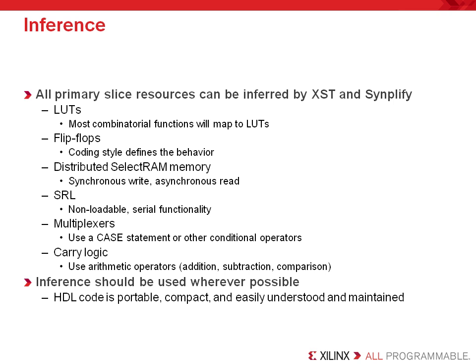Likewise, the shift register LUT is non-loadable, has no reset, and again only supports the serial functionality. So if you code for a parallel read, you'll get a pure register implementation rather than getting the lookup table reprogrammed as the shift register LUT, and this won't be what you expect and will waste registers.